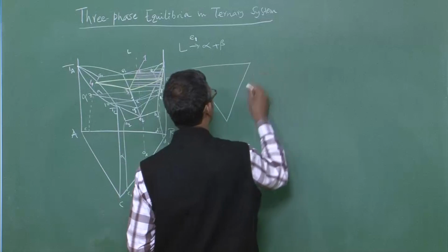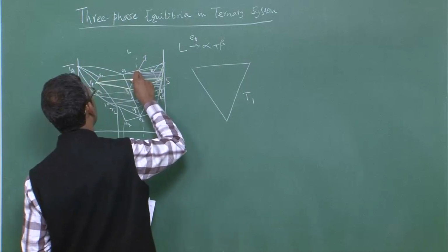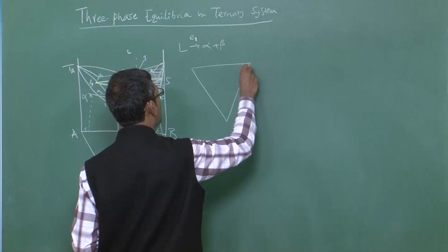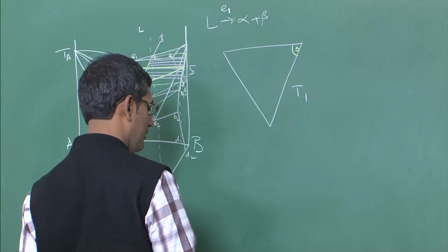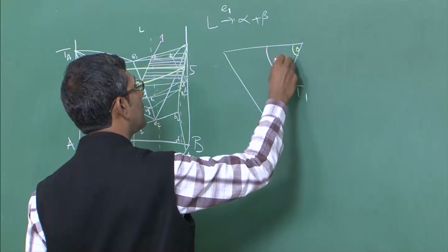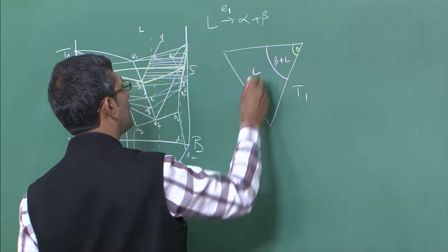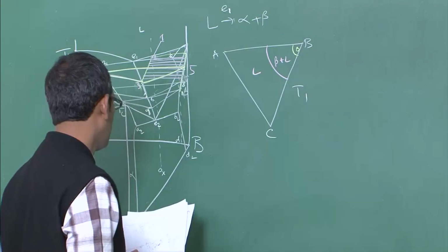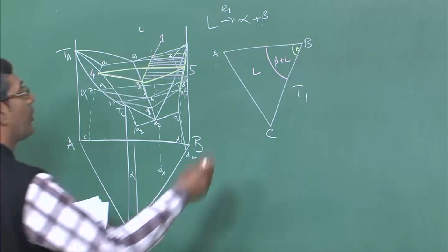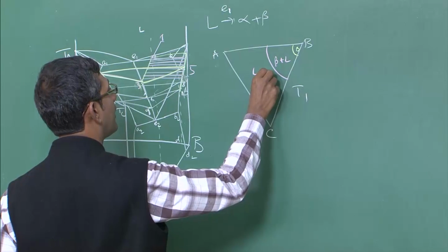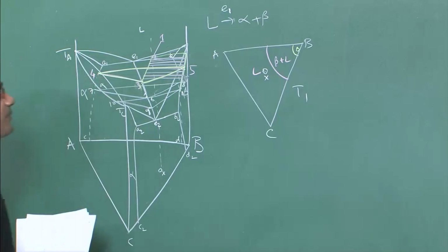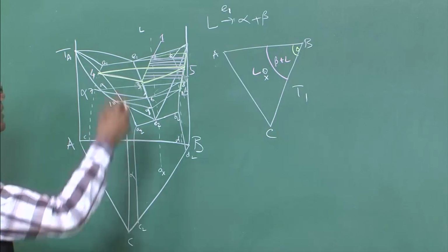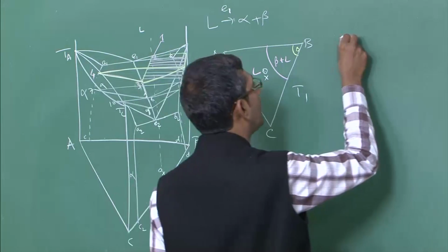Okay. So, this is at T1, suppose T1 means the temperature corresponding to 0.1, and obviously at this temperature you have beta, and then you have beta plus liquid and liquid. Okay. A, B, C. That is obvious. And where is the composition of the alloy? Composition of the alloy will be somewhere there. Okay. I am going to put a dot here like this. So, this is my X. So, at 0.1 basically everything is almost fully liquid, there is no solid, because it is just touching the liquid surface at T1. At T2 what will happen?